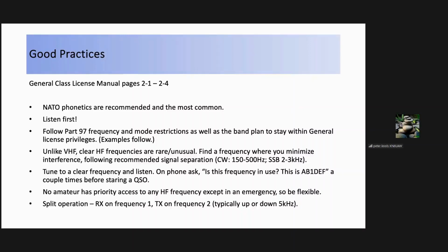And then there's a question on split operation. Split operation is typically used by contesters. And what that means is that you are listening on one frequency and you're transmitting on a different frequency. And so the idea is that you can continue to transmit. Other people can hear you while you're transmitting. You'll only hear them if they dial to the frequency that you're listening on. And in a contest, folks are typically listening anywhere but roughly 5 kilohertz up or 5 kilohertz down.